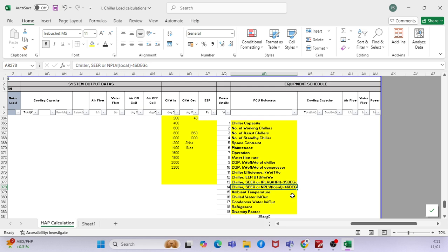That is one of the factors. But there are always two scenarios. When you go with lesser performance, your price will be cheaper. When you go with higher performance, your price will be very high. So that is also one of the concerns. Some clients go with a low efficiency chiller, so they pay a lesser price, and they check what the operation cost is during the year. They will try to balance that operation cost and the chiller pricing. You understand what I mean?